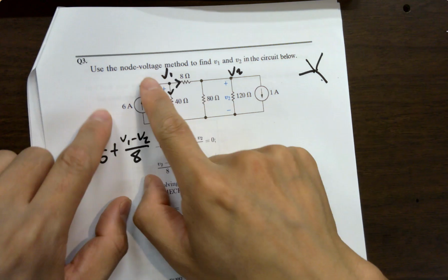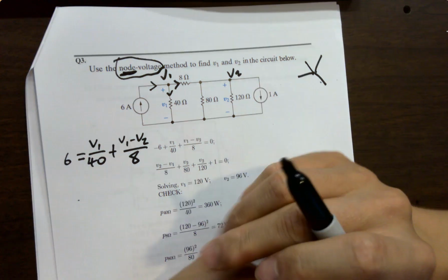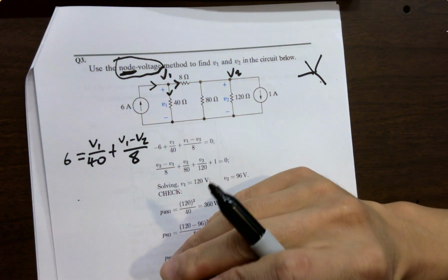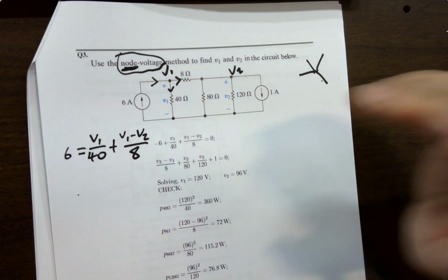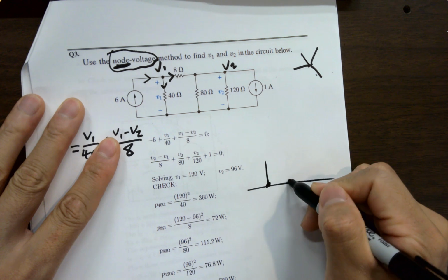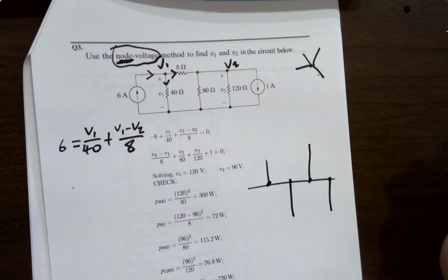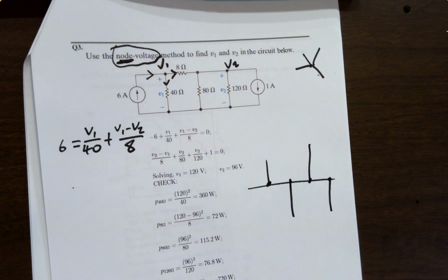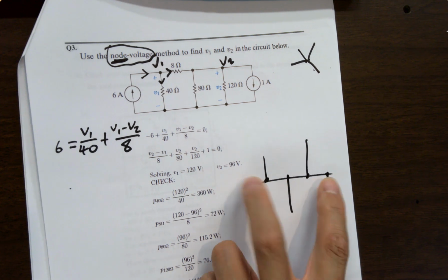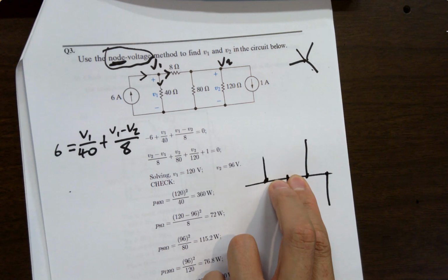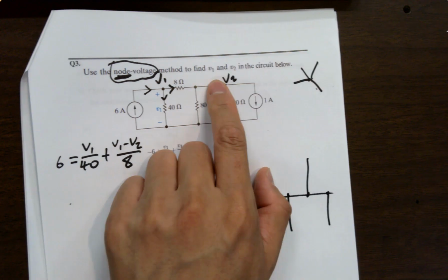So why is it called node voltage? What does node mean? If they are shorted together, no matter how many branches, you got a wire, you got like millions of branches, right? It's still one node. Could you understand that? It's just one metal piece. So you can always imagine that you can melt it and it becomes just one metal piece. Okay? That will simplify your calculation a lot.